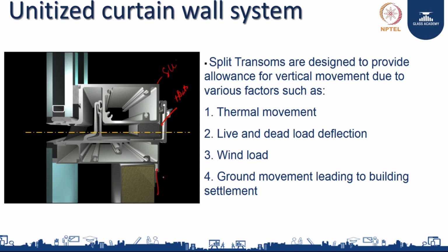Then live load and dead load. Whatever loading you have to consider while designing the building. So there can be an impact load, there can be a dead load. Of course, the dead load is the self weight of the panel plus the factors. What do you call live load? Live load can be human impact, plus your wind load, plus the other loads we consider. We have to add all this together, and you have to arrive at a factor that has to be considered in the design.